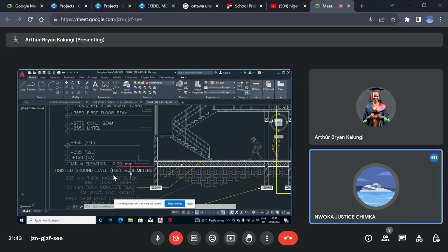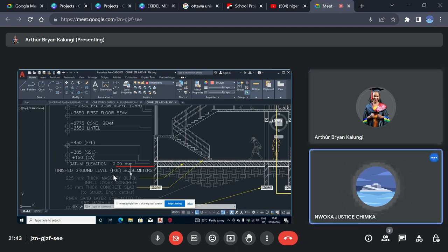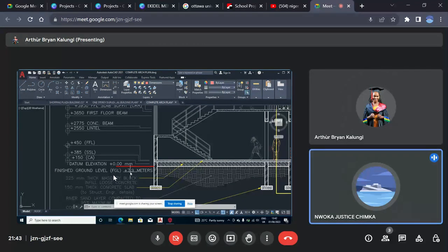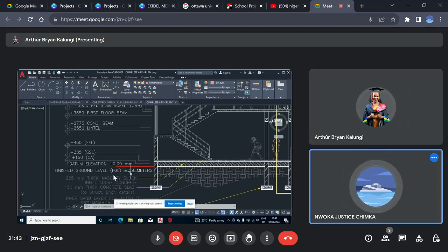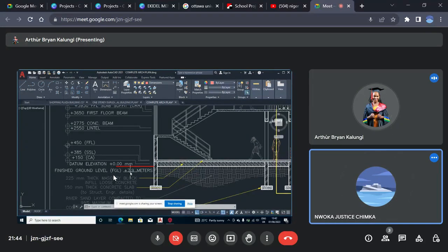Else, if you build like that, when there is a rainfall, all the rain from the bed will flush down into your land, right? So for you to avoid that kind of issue, you must make sure that the tiles have the same level with the bed before you begin any building. You have to go and buy soil or sand to backfill here and fill it up to the level that you want.